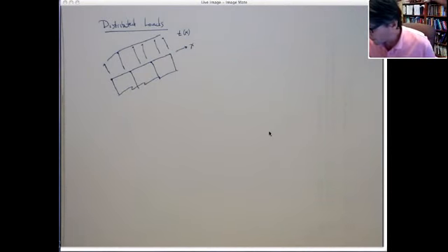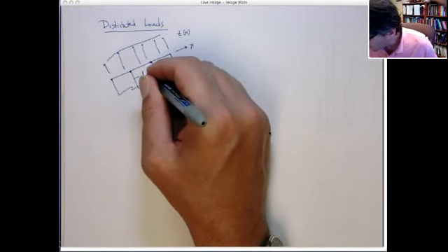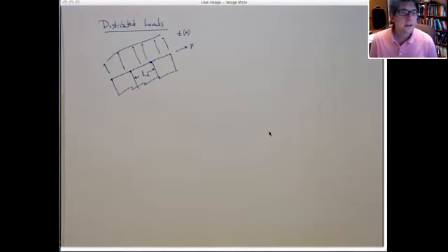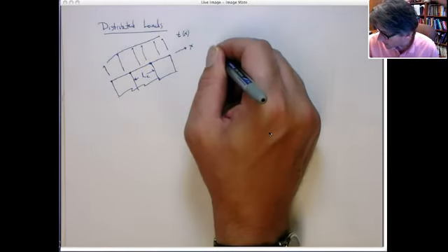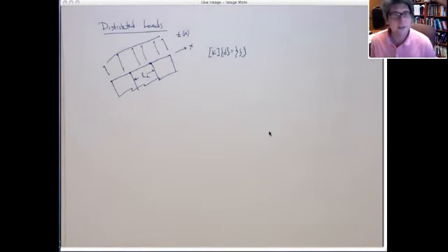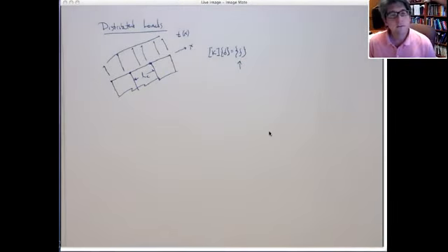Now, one temptation might be just to put point loads at the nodes. And in fact, no matter what you do, you're going to end up having point loads at the nodes. This is the KD equals F, right? We've already shown that that's the discrete finite element equations. So how does this distributed load correspond to the discrete nodal forces F?